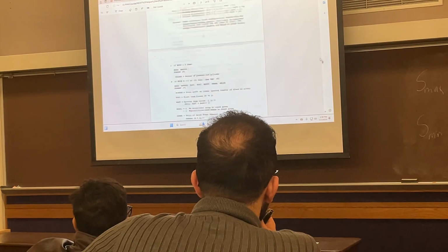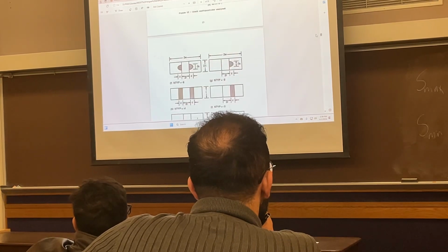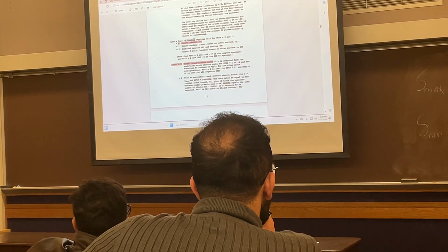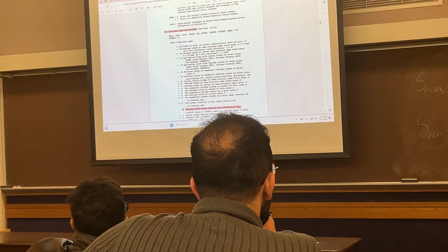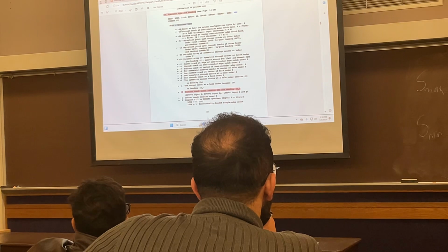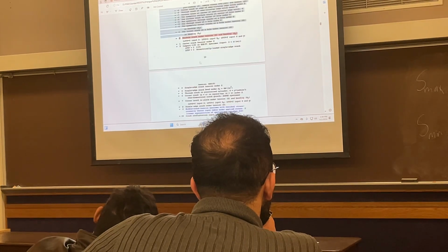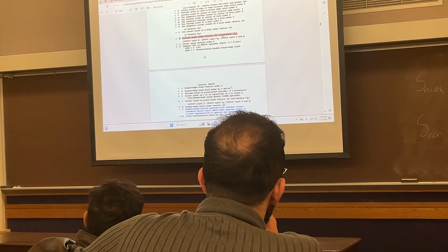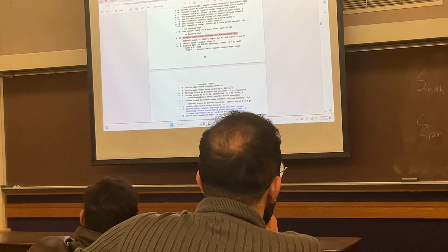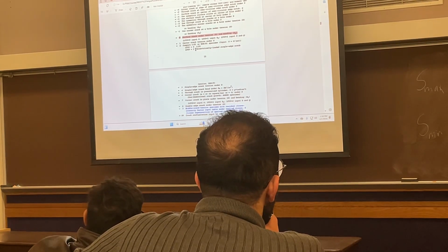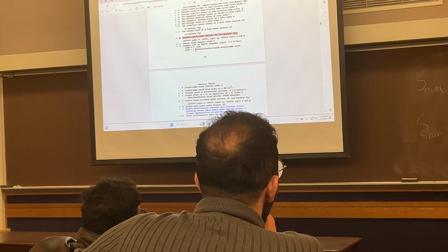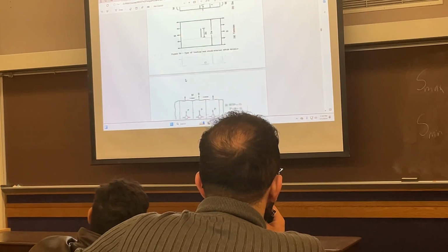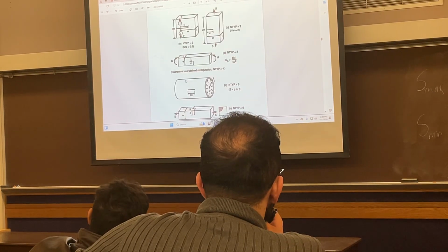So somewhere here, variable amplitude loading, there are many options, but you're using a portion of this code. So these are the different types of loading and specimen type that you can have. This number basically refers to different conditions. For the input file that I gave you, it was a surface crack under tension and bending. So it's 0. But it may not be the case, for example, when you have the corner crack or when you have that bending. So you need to check these, and also there are some drawings to see which one is your case.